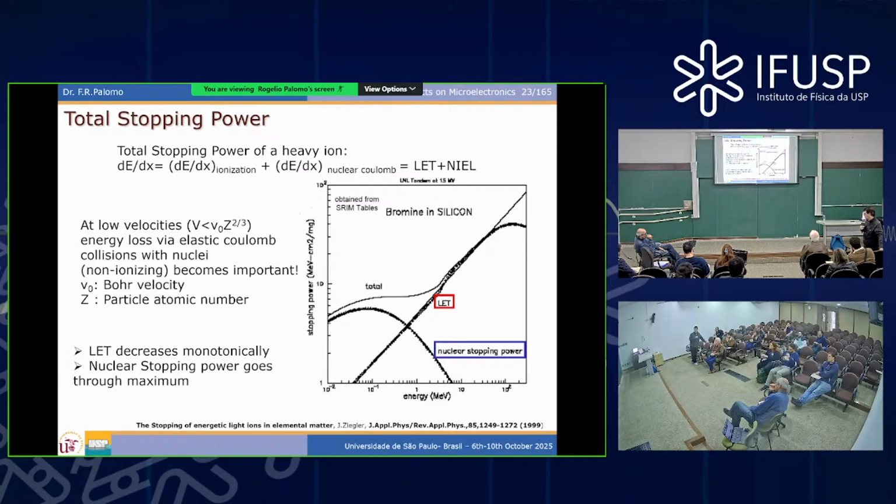It was refined during those 30 years in the foundry that IBM had in New Jersey in the US, because they were interested in the diffusion of dopants in silicon, which is made with a small accelerator shooting ions against the silicon. So they were interested from the very beginning, not for consideration of TID, but for manufacturing consideration. So SRIM is very acceptable.